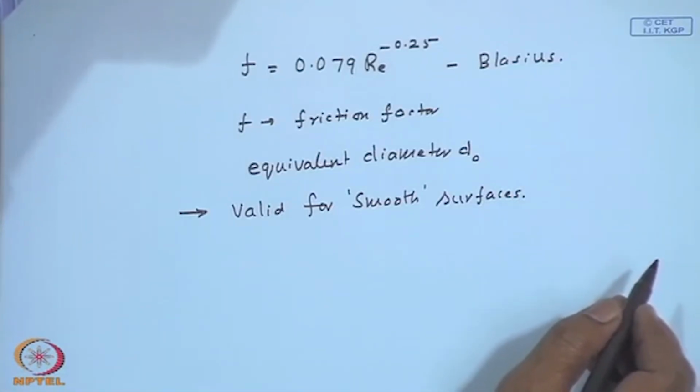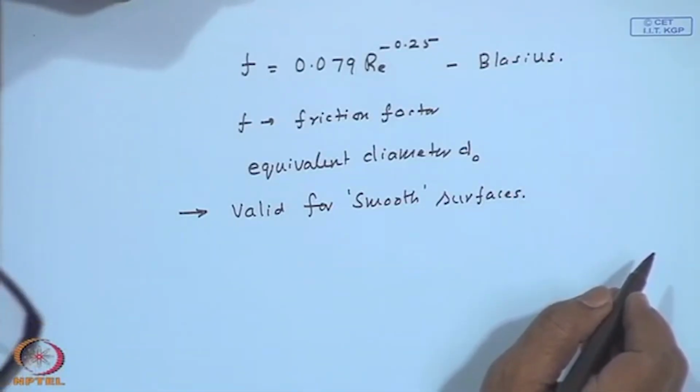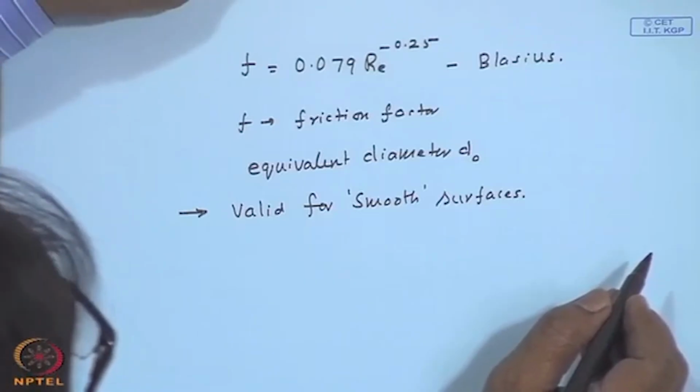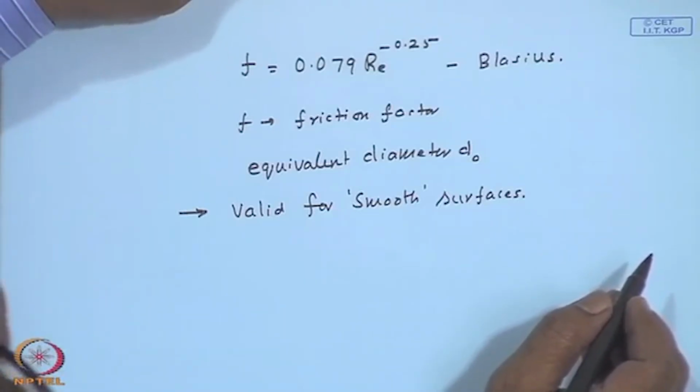So, we have methods to calculate, or the formula to calculate, the heat transfer coefficients in the air ducts and the friction factor, and hence calculate the pressure drop in the air duct and find out the pumping power needed, and compare with the energy gain, and make sure that the energy gain is significantly more than the pumping power required.